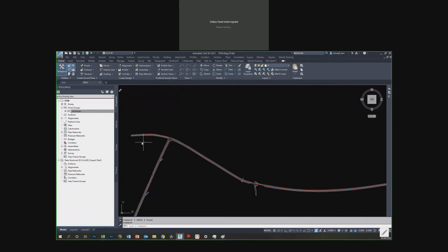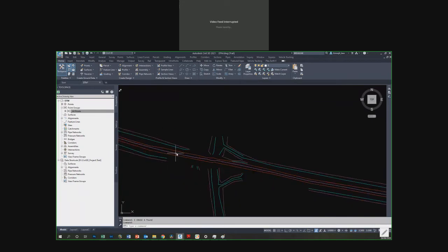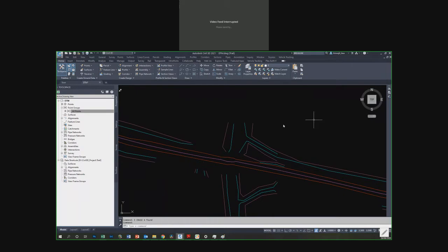Now the point where we started, why we need to remove the crossing lines. Whenever it is a break line, it will have a level. Now, if my two break lines are crossing like this, this break line on the surface will give you a value of elevation. Say, for example, it is going from 100 to 99, so it will be in between 100 and 99.